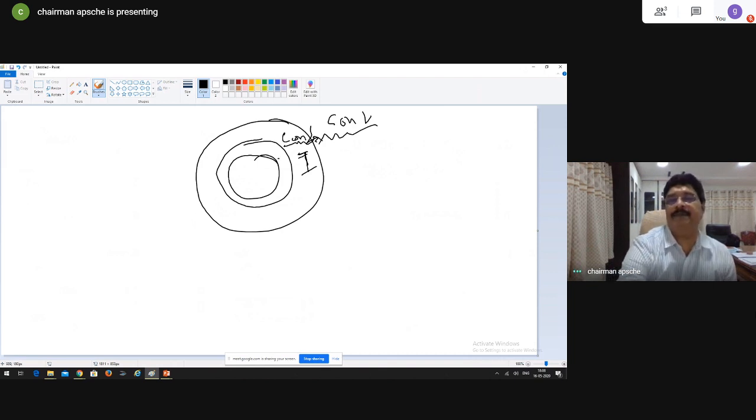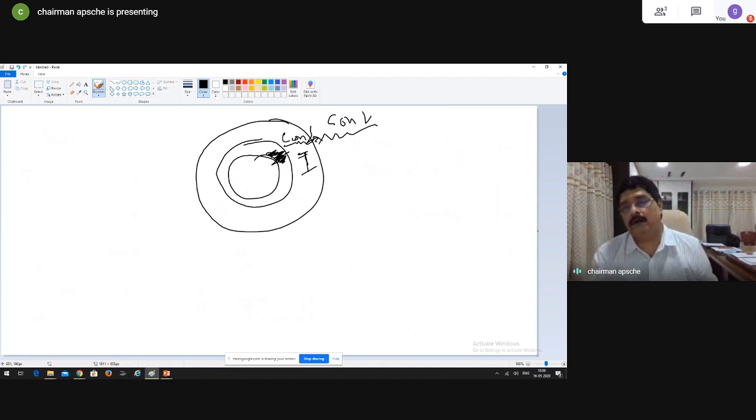This is the pipe. This thickness, where my finger is, filling the gap, is the thickness of the pipe, metal pipe, let me say. On top of it, you have added insulation. So when you add insulation, I am talking about outside insulation, as we have discussed it, critical radius of insulation. When you add it outside, conduction resistance increases, convection resistance decreases because of increase in area.